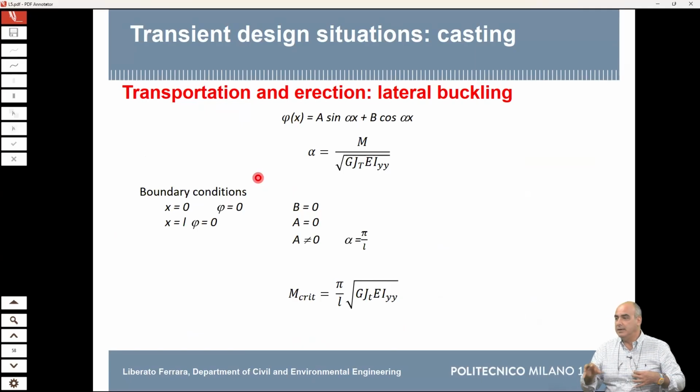And you can immediately have an idea, because if you have for precast, as we said yesterday, standardized shapes and dimensions, you can go to the website of the precaster and you find the beam shapes and dimensions that you have. You can already have an idea, and you can make a very simple assessment, which is the span range I can go into for this.